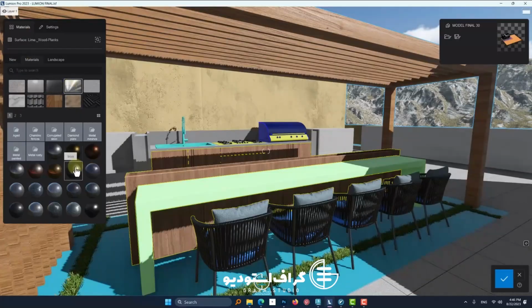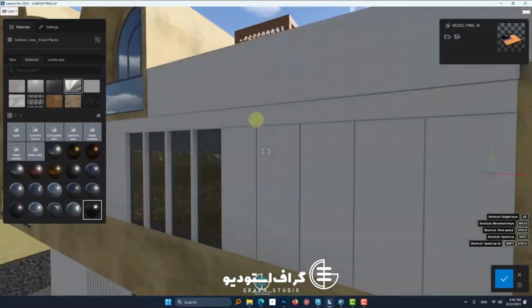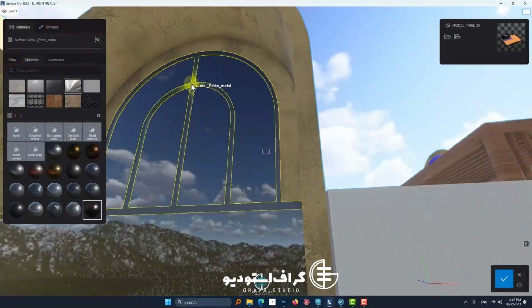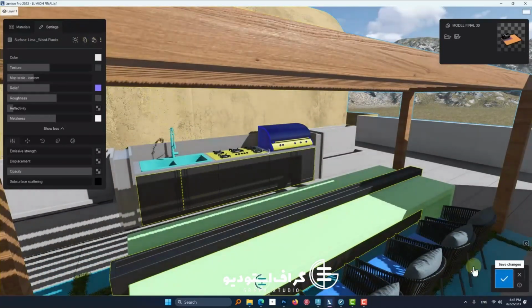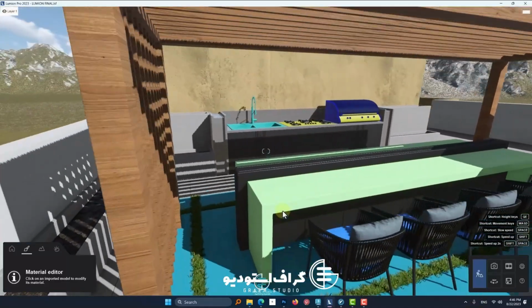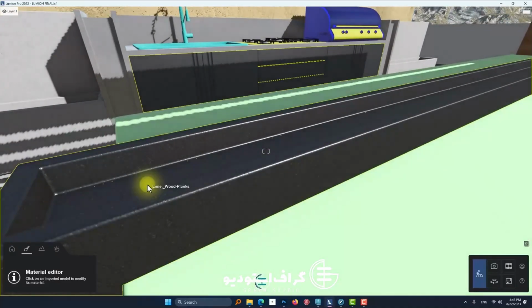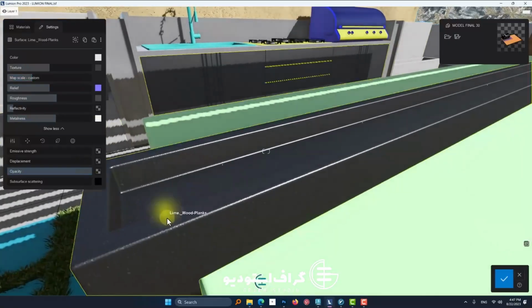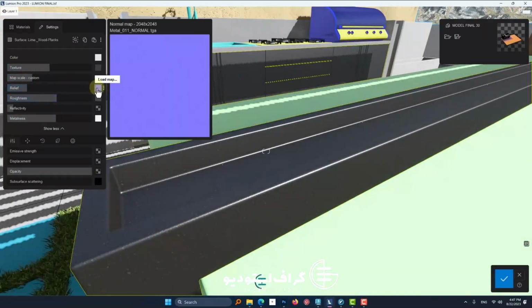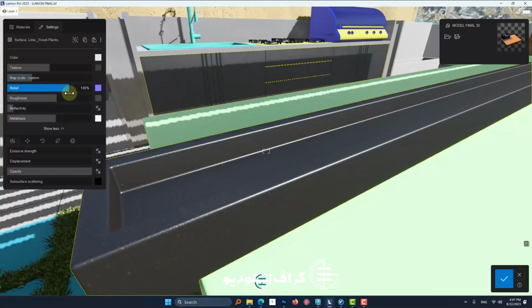For this section, we decided to apply a tile material. I go to the stone pavement section. These are the options available. This one is fine. We will return to it if we don't find a better one. We try to apply a few materials like this in Lumion because it quickly shows the result, and there is no need for a re-render. This one is also very good. Whichever one you apply, adjust its scale. Its placement method is the same as our UVW map.